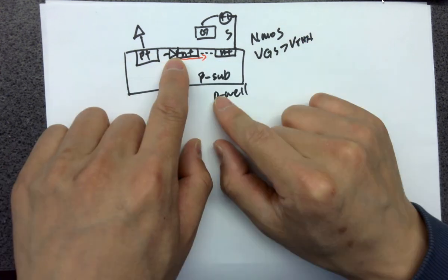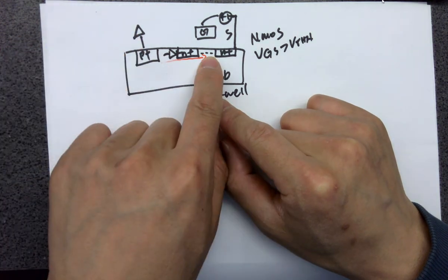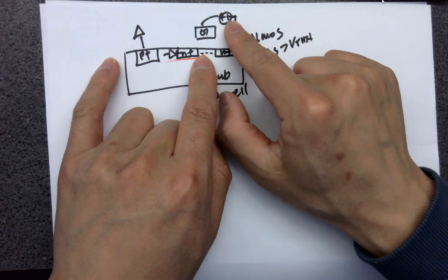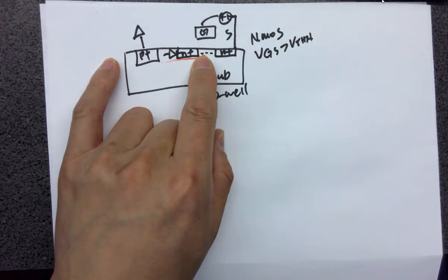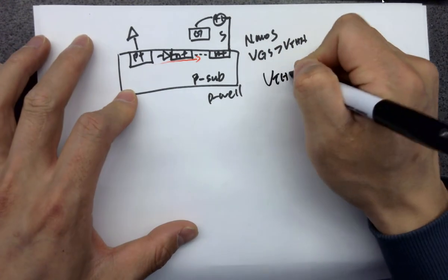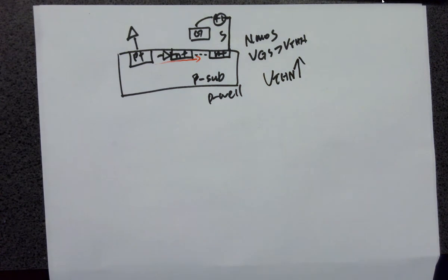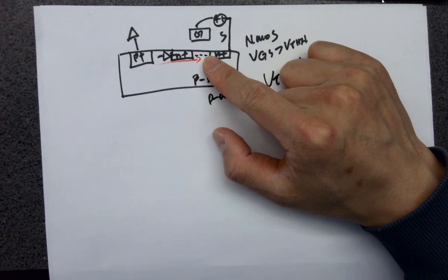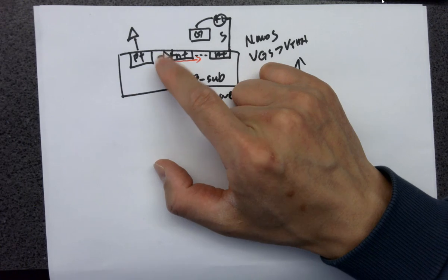And this parasitic diode, because of the body effect, is injecting holes into the channel to cancel these generated electrons, which makes the circuit harder to turn on. So the consequence is your threshold voltage will increase, because it takes a higher VGS to turn on the channel, since some of the carriers are getting canceled by this parasitic diode because of the body effect.